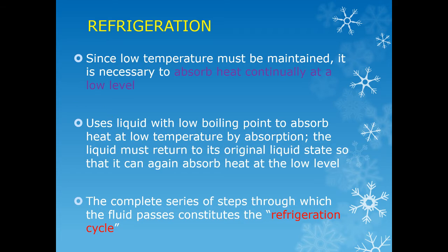Since a low temperature process must be maintained, it's necessary to absorb heat continually at a low level. So it uses liquid with a low boiling point to absorb heat at a low temperature by absorption. But the liquid must return to its original liquid state so that it can again absorb heat at the low level.